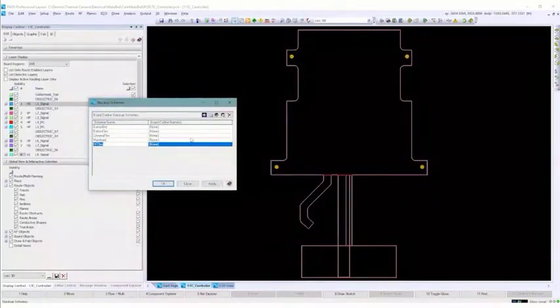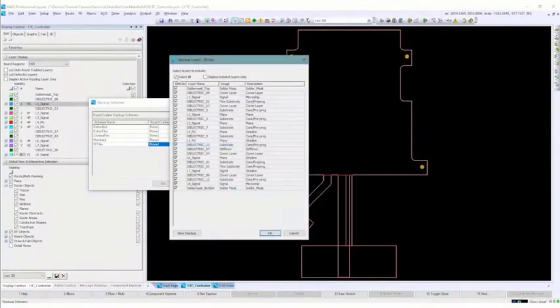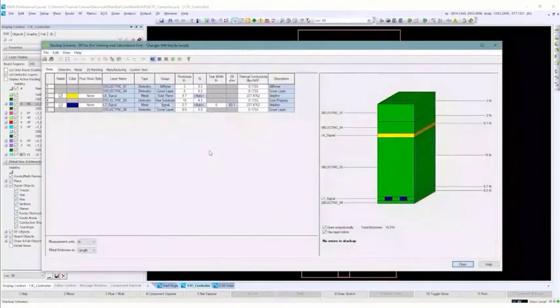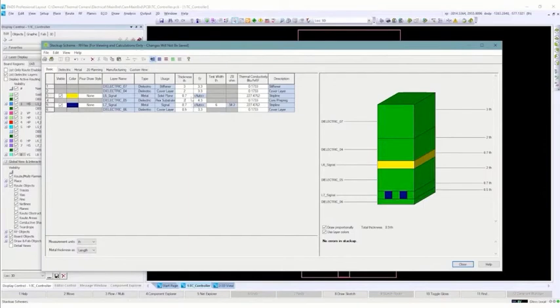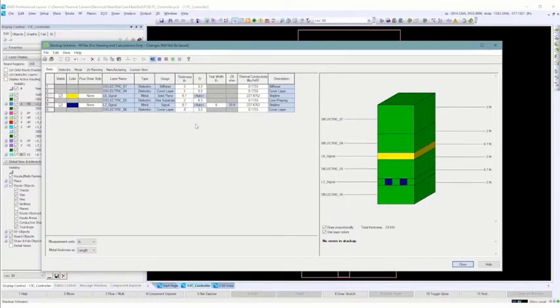Next, we'll do our RF flex stack up. So we click on that. Easier to turn all these off. And then we can select the stiffener, cover layer, plane, flex substrate, signal, and cover layer. Again, we want to view that stack up so that we can adjust the thickness of items, like the stiffener being 3. This doesn't need to be 10. That's 2. 1/2 ounce copper. This needs to be 2. All right. Again, it'll tell us if we have any violations. So we have a cover, signal, dielectric, signal, dielectric, and our stiffener.